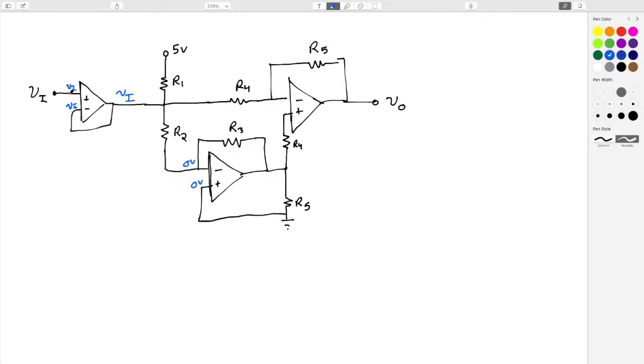So we figured out, okay, these are tied together, this goes here. Another way you could have done that is just said, this is a buffer operational amplifier, a gain of 1, so whatever the voltage is here becomes the voltage here. Either way you arrive at that is fine. The next step I'll do is I now know that the node voltage here, and I know I'm actually using V's in here instead of the E's, but I just like to use V's a lot of times for voltages. But anyway, we know the node voltage at this point in the circuit is VI. What can I do with that?